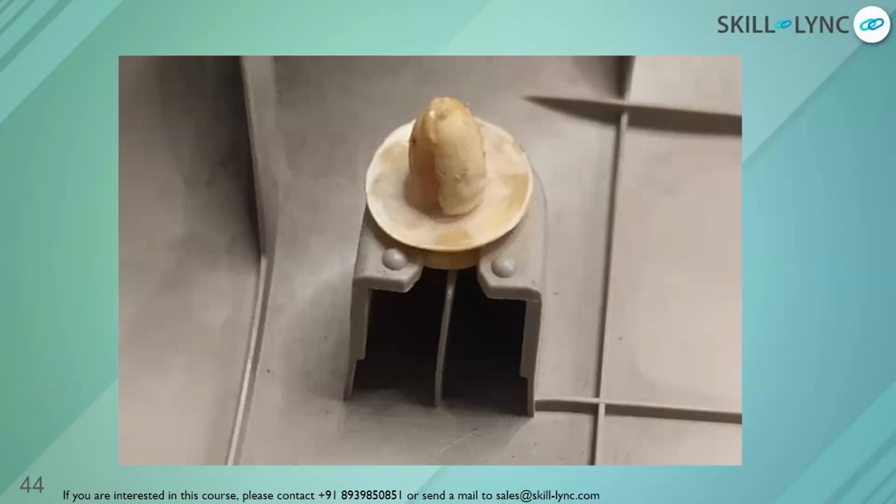So hence we are going to join this plastic component, or the assembly of the plastic component, with the sheet metal part using temporary joints, and hence we find the use of push clips. This makes sure that proper fixing is available with respect to the sheet metal part, but when there is a requirement for serviceability, we can remove it. These are simple plastic components, and if there is any damage to this part, we can replace it also. Correct. So that is the use of push pin, push clip, and the doghouse arrangement here.